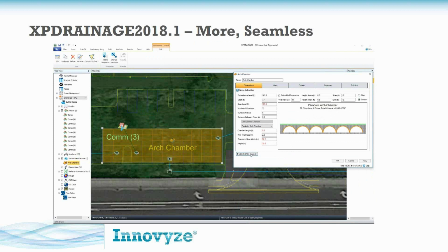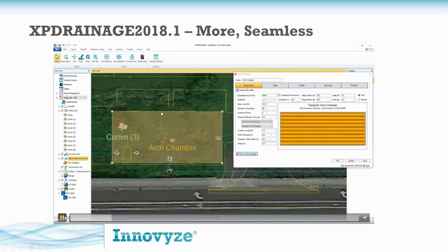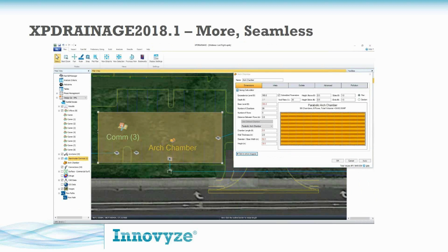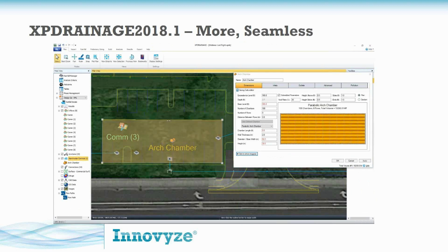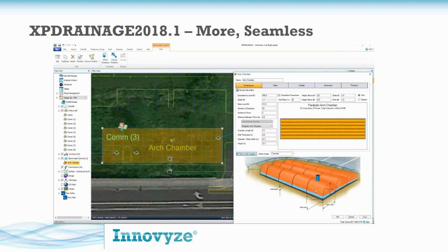And chambers are pretty funny little structures, right? They're not like a pond or a swale. They're these little compartments, right? So as you'll see when I play it one more time, when we move the layout, it only snaps to the complete sections of pipe. We couldn't order three quarters of a length of one of these chamber sections, right?